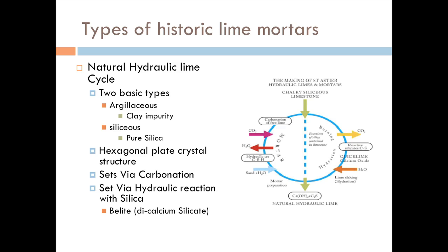And what this does is that when the limestone is burned, when you have a siliceous limestone and you burn it, that silica inside of that limestone ends up becoming reactive. And it gives it these hydraulic properties, which is pretty unique because you don't run into hydraulic limes or what's called natural hydraulic limes very often.